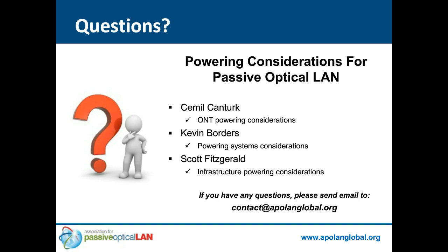It is a consideration. It's going to vary based on the amount of DC power that you have at the site. And you also have to be sure that your equipment room either has AC or is well ventilated, because the devices themselves can operate over a fairly wide range, as can the battery.